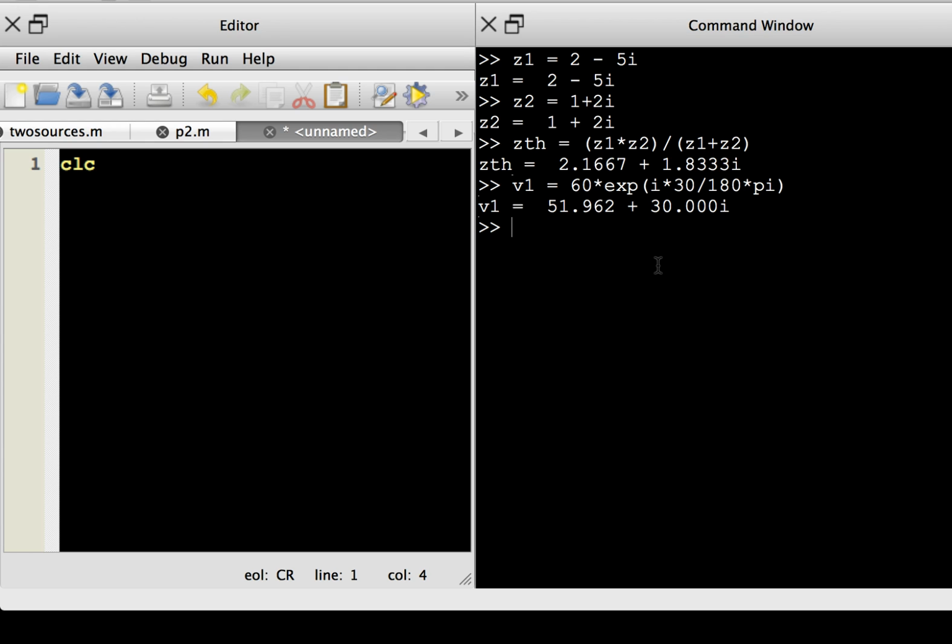So this is how I define V as a complex number. Luckily V2 is just 0 degrees, so it's just 50, I can use it. Now I want V1 minus V2 divided by Z1 plus Z2. This is the total current, and this entire thing multiplied by Z2 will be the voltage drop. So minus 15.32 minus j4.01.